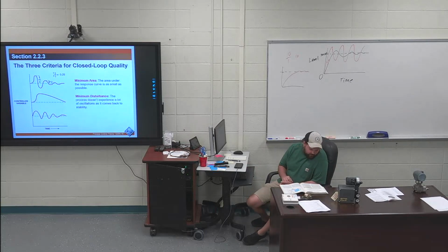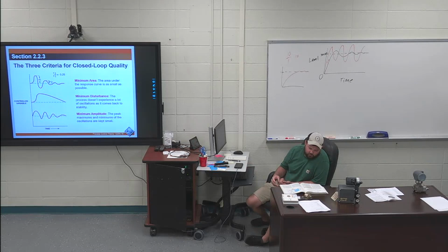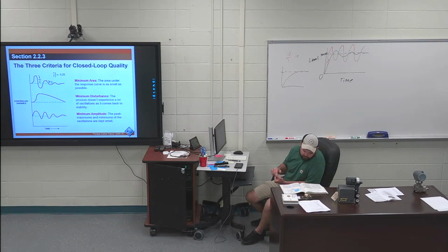Page 20, all the way in the top right of the page, I've got 3 different highlights. Each sentence at the top right of the page is a separate highlight. First highlight, cascade control is a modified form of feedback control. Second highlight, a single cascade control system has 2 control loops. And then the third sentence, the task of one of these control loops is to maintain the process variable at a desired value. This loop is called the primary or master control loop.